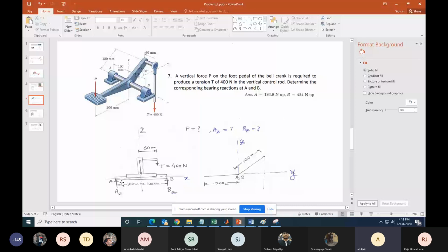Sir, because all forces are in the Z direction, then you are considering that along Y direction force is 0. Then I can only say AY plus BY is 0. I cannot say AY and BY individually are 0. That I cannot say, sir, but I can say AY plus BY, the resultant force along the Y direction, is 0. Sir, we have only assumed that, or there is something else. I think we are assuming that this question otherwise is statically indeterminate.